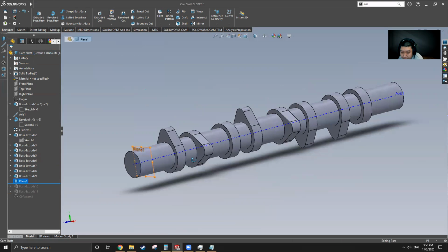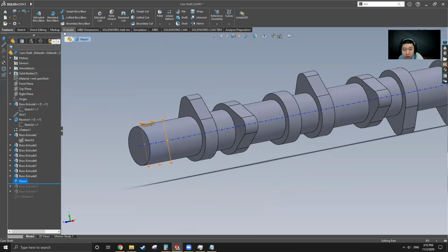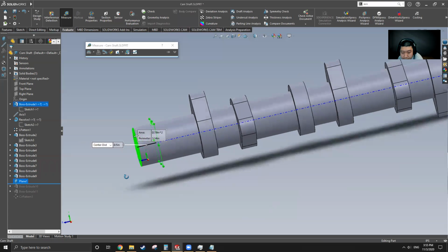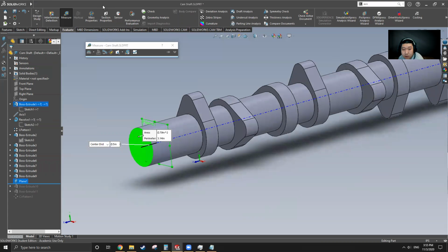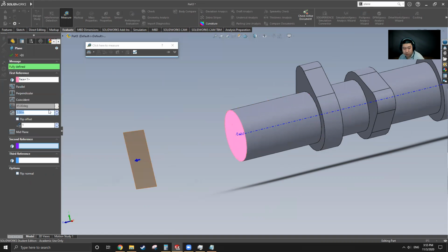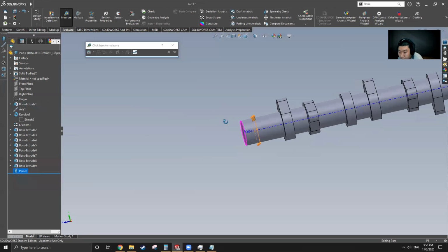So we're gonna make a plane from the tip, and how far away? 0.5 inches inward. Okay, then let's make a plane. So again, either click here or search plane. Select this as the initial reference and modify this to 0.5. And flip the offset because we want it to be inwards, right? And here we go. We have our plane.